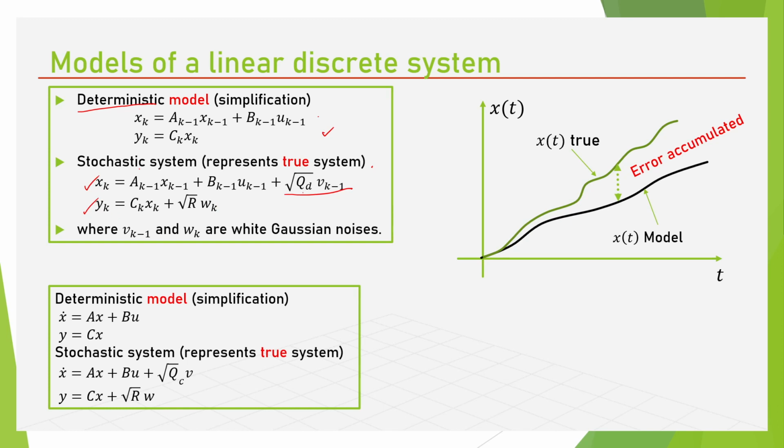For a linear system, what we can measure may be part of the state that describes all the motion and dynamic behavior. Let's take the motion of a mobile robot. To describe the whole motion, we need 6 variables: position x, y, and orientation, then the velocity along x, the velocity along y, and the angular velocity of rotation in 2D.